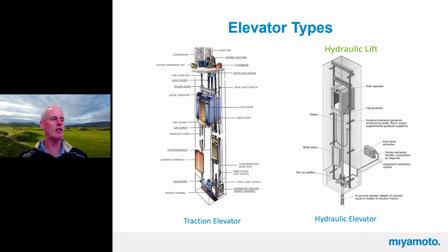You can certainly attach the guide rails to wood, but it's a bugger of a detail. So I think I kind of like that system a lot now if you have a wood building. And really for 2 reasons. One, our connection details are clean, they work. It's hard to anchor some of those forces into wood where you don't have a lot of room, or you have to do a bunch of goofy strapping and stuff.